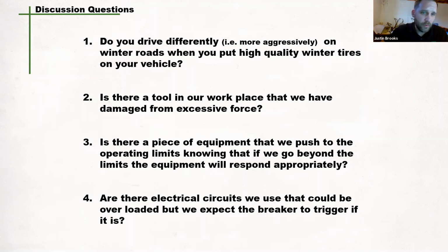Again, even for question number 2, is there a tool in our workplace that we have damaged from excessive force? We've seen that pipe wrench a few slides ago. Think of every time that you've ever used a snipe. For those that are unaware of what a snipe is, it's to increase the leverage on something. For example, in that picture of the pipe wrench, I'm thinking that a snipe was probably used, where you'll have, say, a 36-inch pipe wrench and you put a 6-foot piece of pipe on it so you can get more force to increase that leverage. Well, that tool is not meant to be used in that way, and to have that much force applied to it. So I want you to really think about those types of things when you ask these questions.